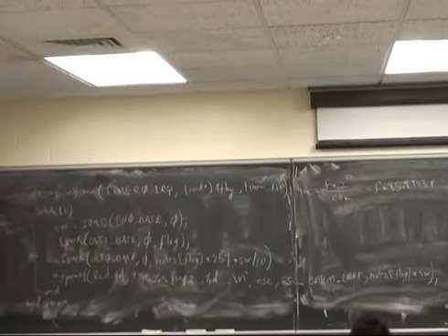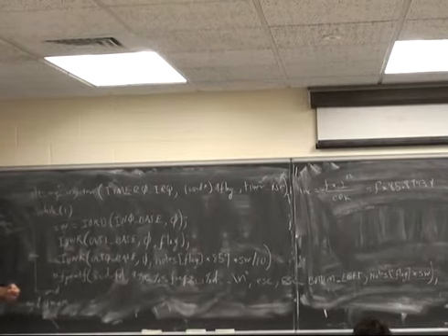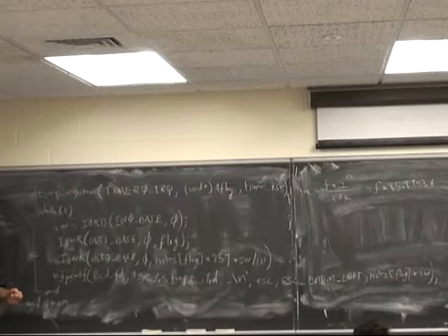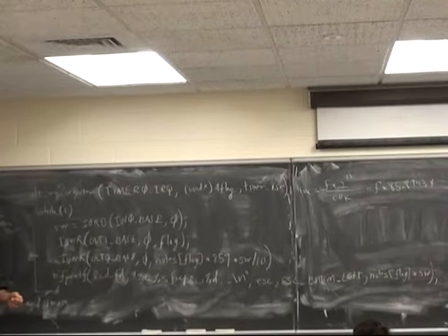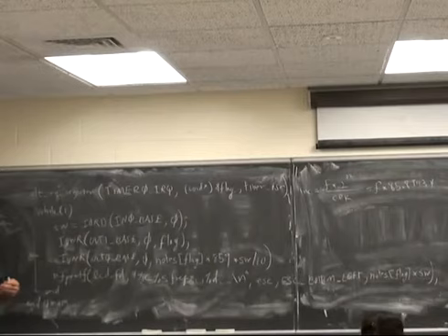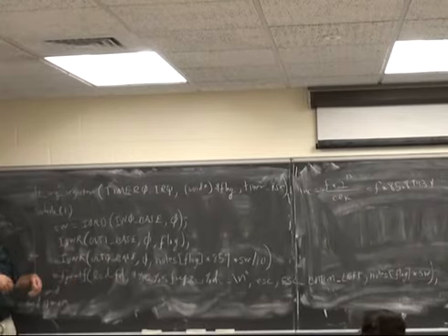So we've sort of gone through the process of building a computer using SOPC Builder, then embedding the CPU into a hardware environment in Verilog. And then once it's embedded in the hardware environment, connected to the switches and the LEDs and the LCDs and so on, then we can write a program for it.